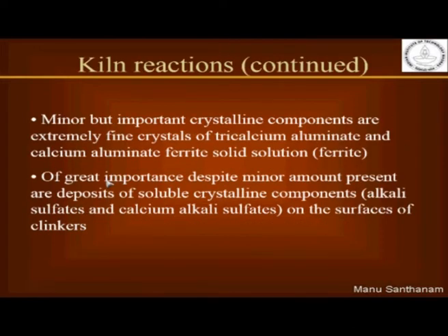But there are also other reactions that take place which lead to very interesting properties of the cement. You form the aluminate compounds C3A, that is tricalcium aluminate, and C4AF, that is calcium aluminate ferrite solid solution. But these are minor compounds that are also formed, but they also have a very large influence on the cement behavior when cement actually reacts with water.